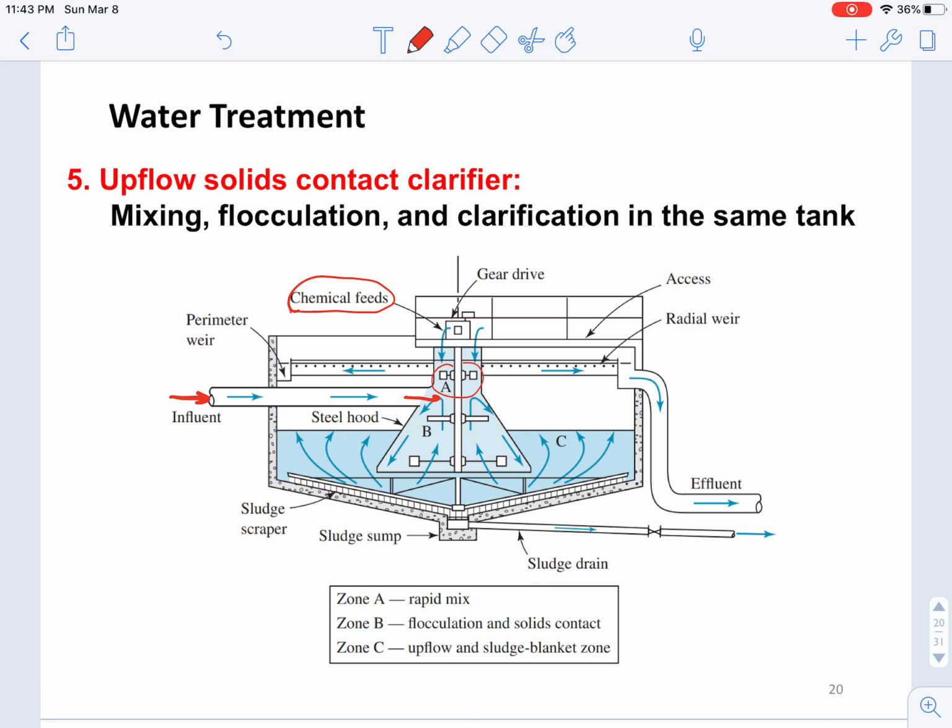And then you can see that this has a conical shape. By having this conical shape, we basically enlarge the surface area. If we have a larger surface area, then the velocity will also reduce, right? Because of that, the baffle here is going to rotate at a smaller speed. At a smaller speed, this will enhance the flocculation so that you're not breaking up the particles while you are still guaranteeing that there is adequate mixing of the water.